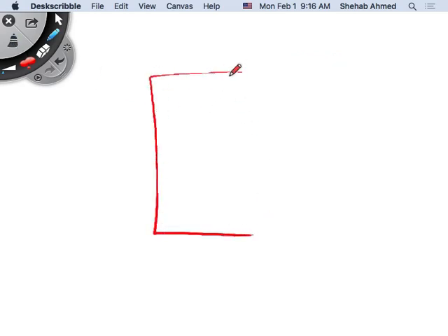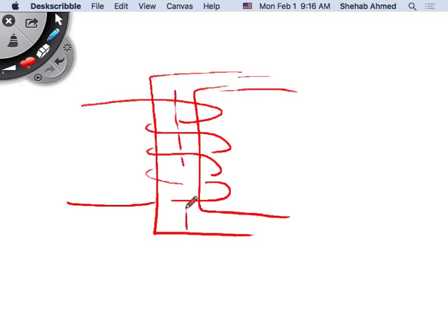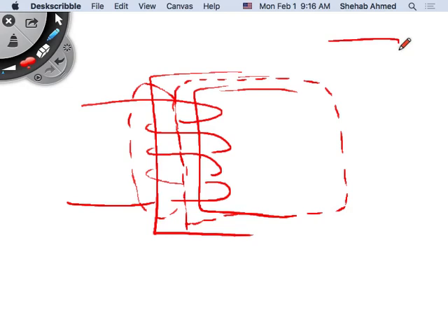If you have a core here and you put windings around the core, most of the flux that's generated by the winding and the current flowing through it will either flow through the core, or the other parallel branch is what? Through the air, right? It's like a current flowing in 2 resistive circuits. This is air and this is the core. It sees air and it sees the core. Some will flow through the air, some will flow through the core.